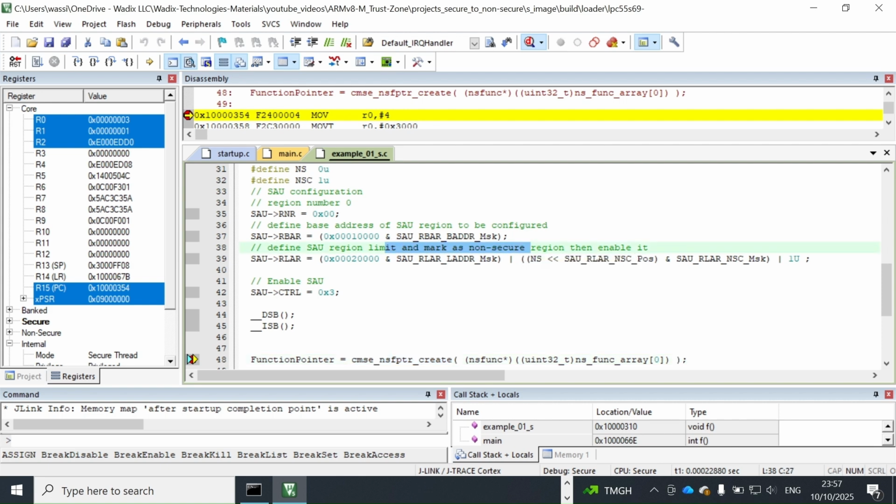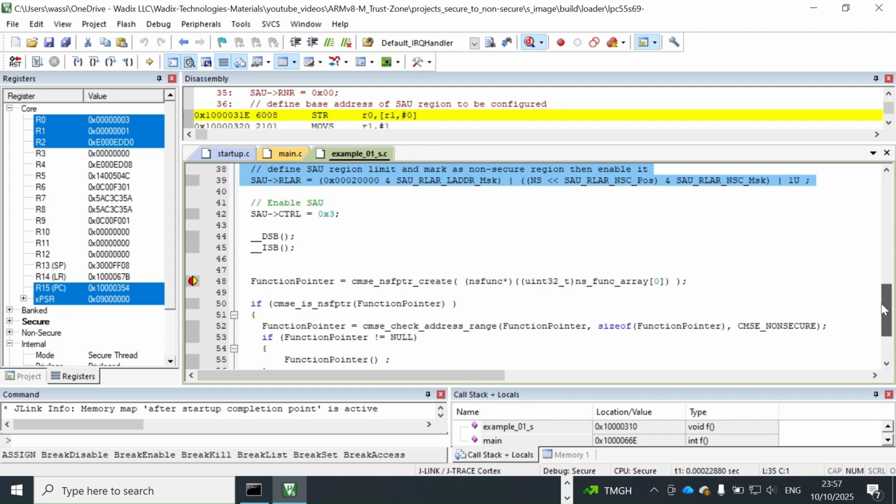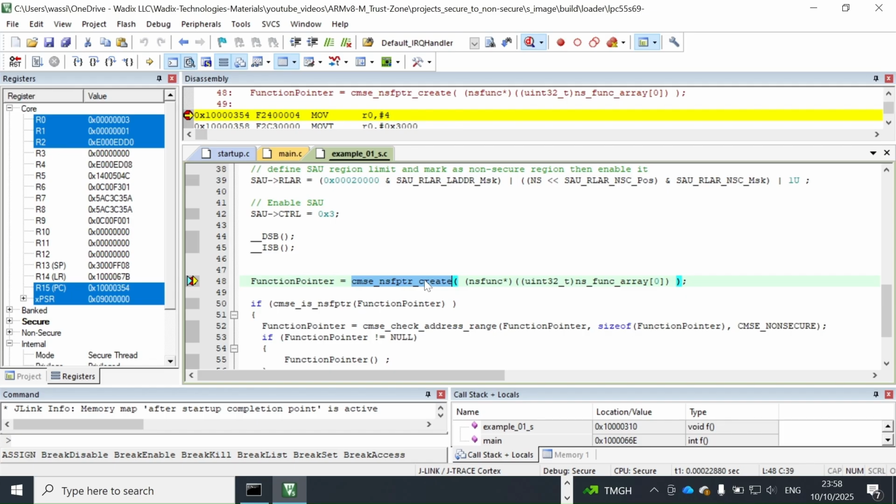This is done via this code. The second condition is to have bit number 0 cleared. This is to distinguish that this branch is meant to trigger a CPU security state transition, and is not a standard Thumb encoding based branch. Hence, we need to clear bit number 0, and this is the job of this macro.